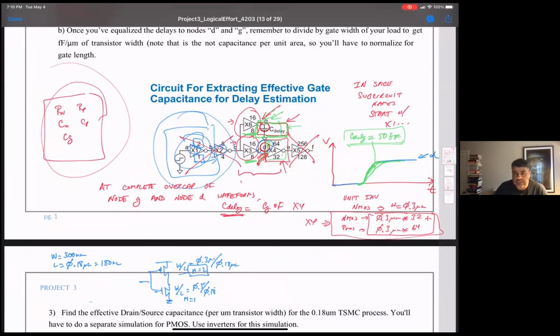Logan, are you doing it in LTSpice or using PSpice? Yeah, I just had the total realization of what you meant by that. So the M factor, because we're just paralleling them, is basically the number of parallel devices. So on X2 there, you have 8 paralleled PMOS and 4 paralleled NMOS, right? Yeah, and then you're guaranteed to be exactly quadrupling the size from X1 into X2.